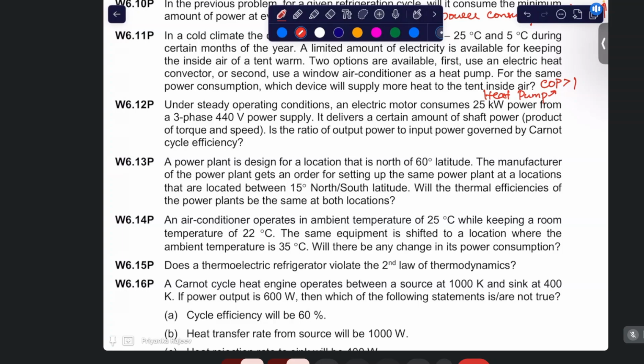Okay, so they are talking about a motor converting electrical energy to mechanical work. So the second law limitation for a Carnot engine is not applicable for an electric motor. The second law limitations are there, but that is not applicable. So motor efficiency is going to depend on electrical losses or friction or magnetic losses, etc. Okay, so the answer is no. Second law limits only heat engines.